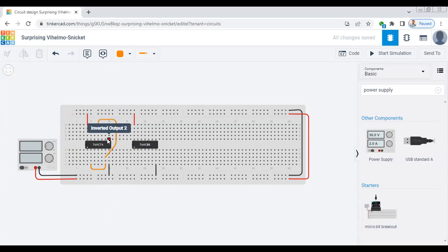This is pin number 8, 9, 10 and 11. Right. So after that, as I already mentioned to you in the circuit diagram, we take the wire in the middle of these and connect that wire to the input of our AND gate. So the input of the AND gate is this one, right? So another connection is connecting the 5th number pin to the output.